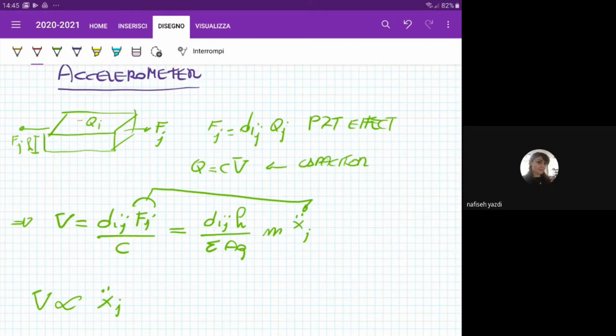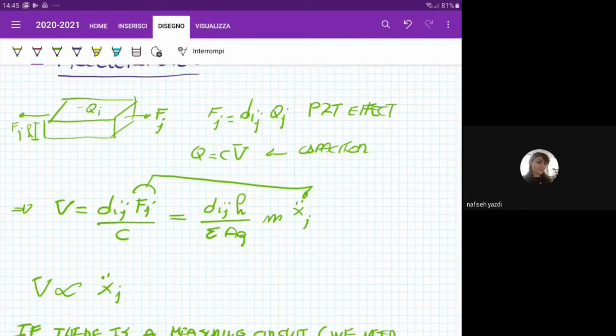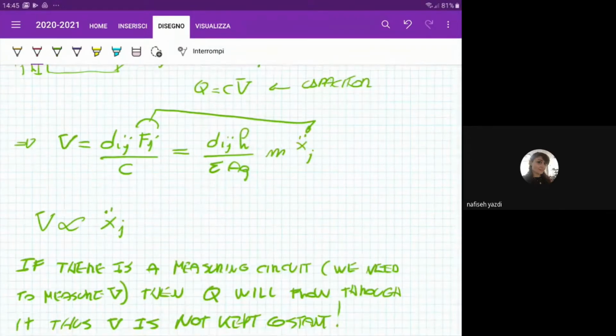That's because we are doing that, we can have charges that are always positive or always negative according to the plane that you are considering. There is a sort of perturbation of this value, but not changing the sign. So there is no electrical flow inside the PZT, and we have a high accuracy transducer, just because the charges are remaining on the same plane, not moving at all.